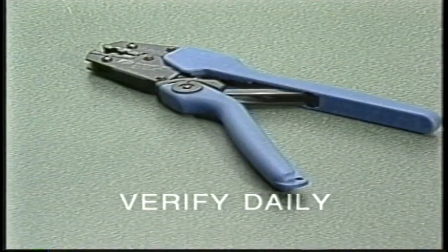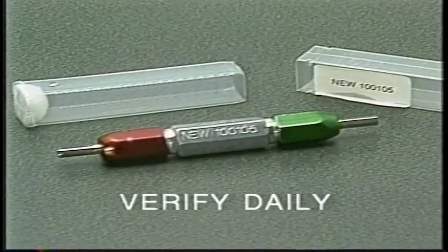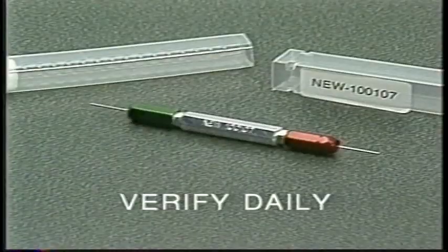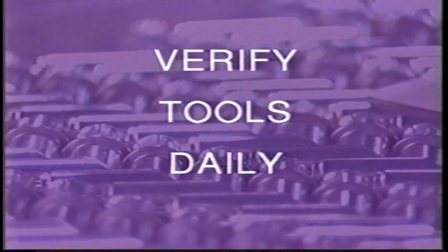It is important to remember that the hex crimp tool must be verified daily before use using the hex crimp gauge. The contact crimp tool must be verified daily before use using the go, no-go gauge. Field verification must be performed each day. If any hand tool fails to pass the go, no-go test, consult the factory for replacement instructions.